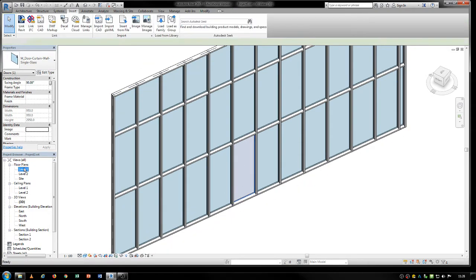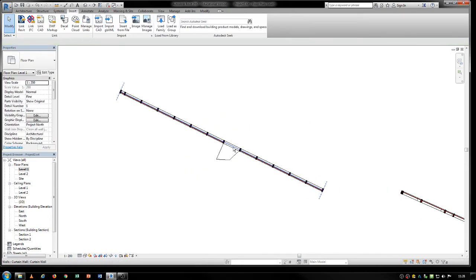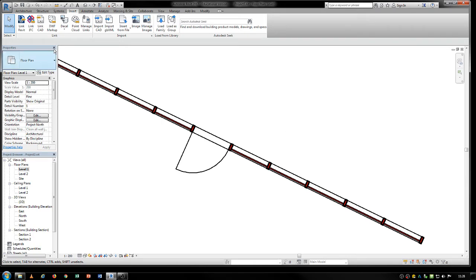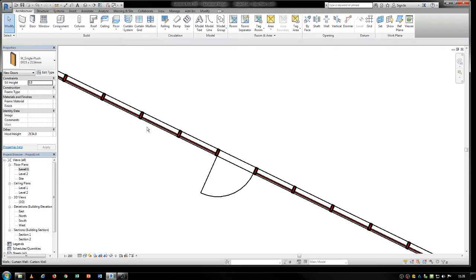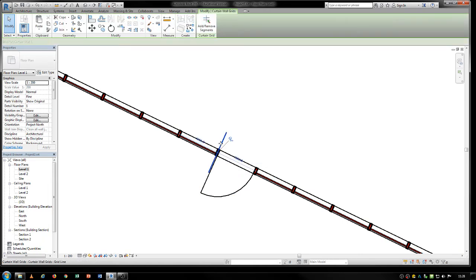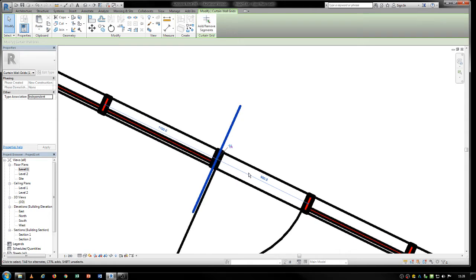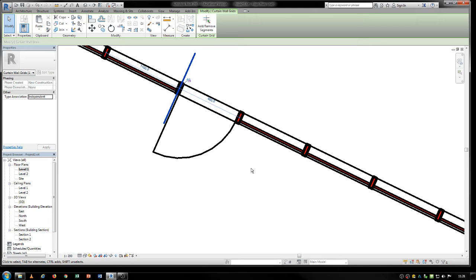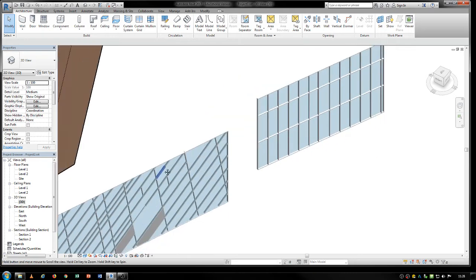Now this is a door. So when I go to my level 1, actually, if I find the thing, so there's a door in my curtain wall. A lot of times you have issues with putting doors in a curtain wall, because that's not possible. Like if you go pick the door, you cannot place this on the curtain wall. You need to define the right dimensions by moving your grid lines to where they need to be. A lot of times they're pinned. You can unpin them, move them around, or give them proper distances. If it needs to be whatever number, you can define it there, and then change the panels to what they need to be. If they're upper bay windows, or there are solid panels, there are drywall panels, there are door panels, anything, you would define them this way. Questions?